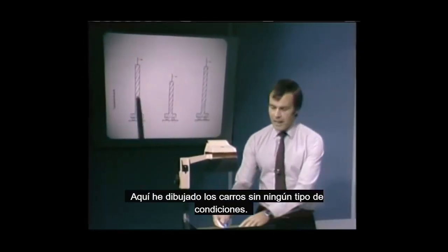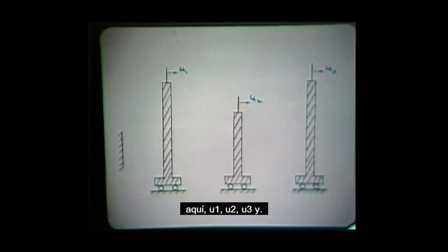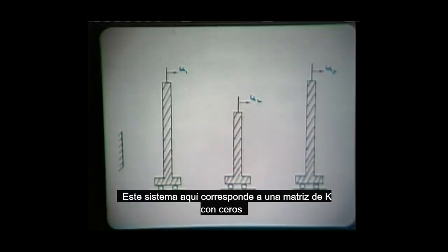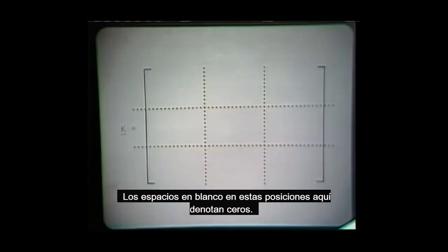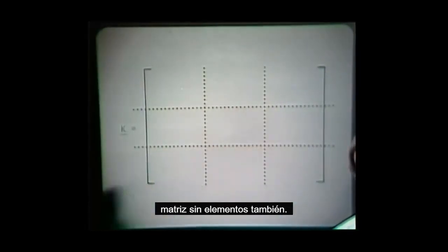Here I have drawn the carts without any springs. Of course, our degrees of freedom are here U1, U2, and U3, and the loads are R1, R2, R3. This system corresponds to a K matrix with zeros everywhere. Blanks in these positions denote zeros. So this is the system that we are starting off with in the direct stiffness method: a system without any elements, a matrix without any elements also.